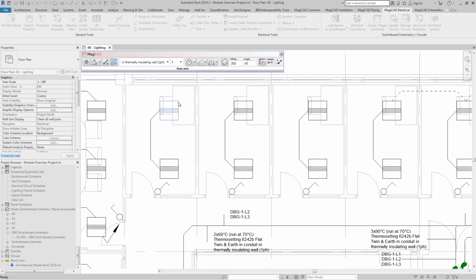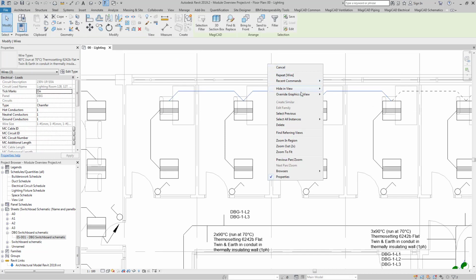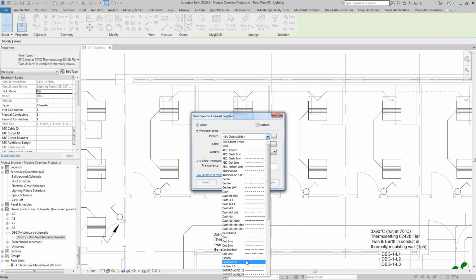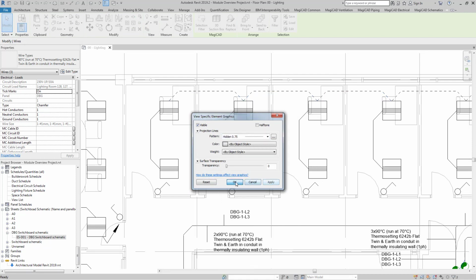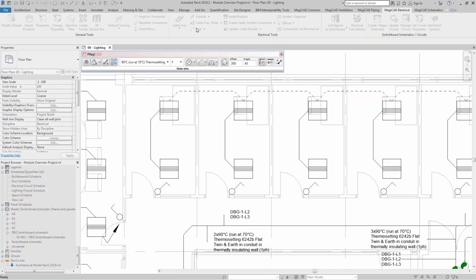We can see by the use of this tool that it's quite straightforward to use even in a manual process, and it's certainly a lot faster than using out-of-the-box Revit tools. Once these are input into the model, they are simply Revit wires and can be adjusted as you normally would. You can also detail other items, for example, in this case, leaders. So to detail the switching within your circuit, you can use the same tool to produce leader lines.